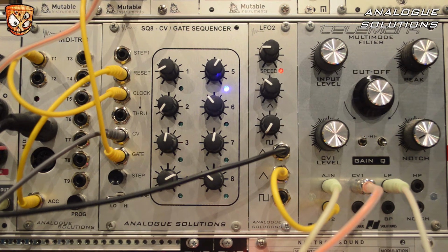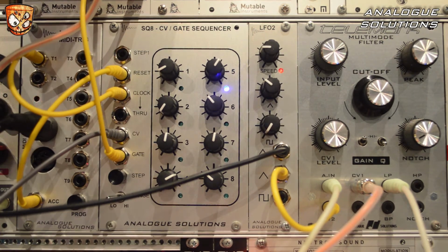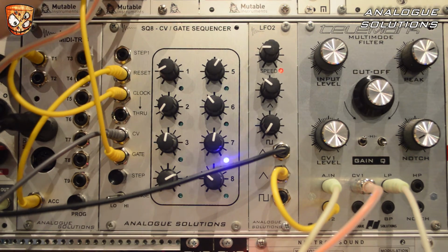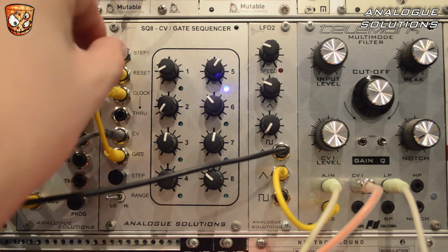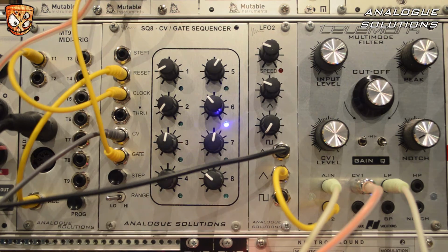And while this is playing, I'll patch up a simple noise hit, which I'll use the step 1 output to accent the start of the sequence. So now you can hear that noise triggering from that step 1 output. The step 1 output is triggering an envelope, which is used to open up a VCA that's got noise at the input. So this noise hit is just simply accenting step 1 and the start of each cycle.